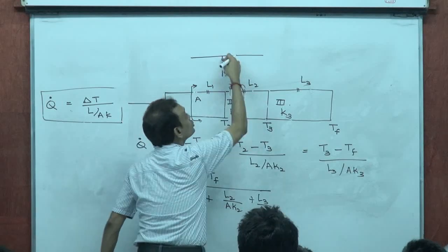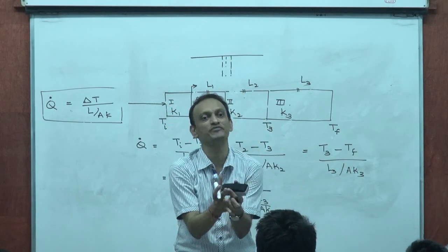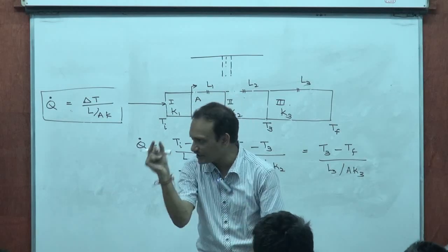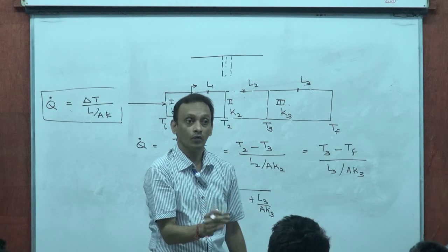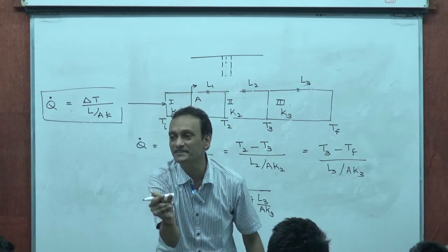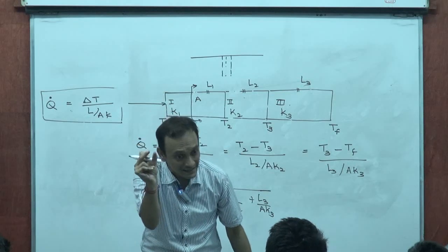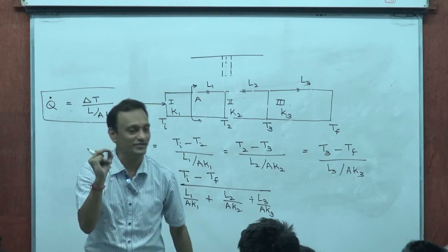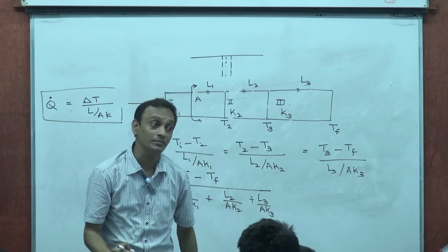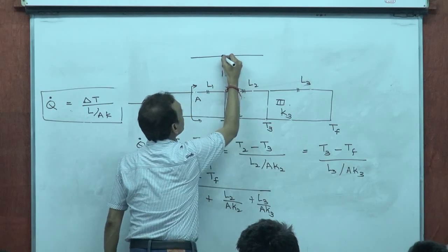That means across this air gap, which you can't see when you're imagining that it's perfectly pressed. But realistically, it could be an air gap, for example, or maybe an adhesive gap. There could be an adhesive which might show up as a small thickness, right? So then, that by itself will offer thermal resistance. And if that offers thermal resistance, then at the interface, the temperature would change.